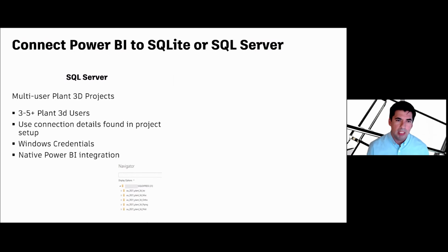Most of the time, if there are more than three to five people on your project, you'll need to switch to SQL Server. The reason for that is as pipers and designers input information, the amount of time required to save and the number of people saving drawings changes how the database can react. And so for those scenarios, you will need to move off of SQLite and use SQL Server.